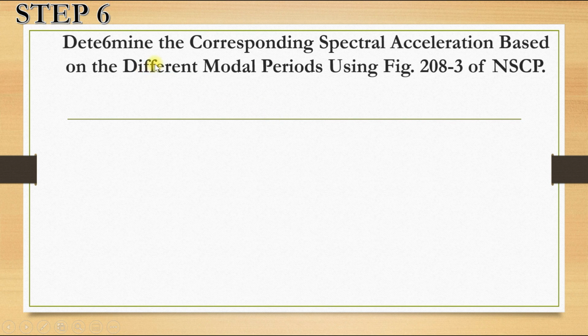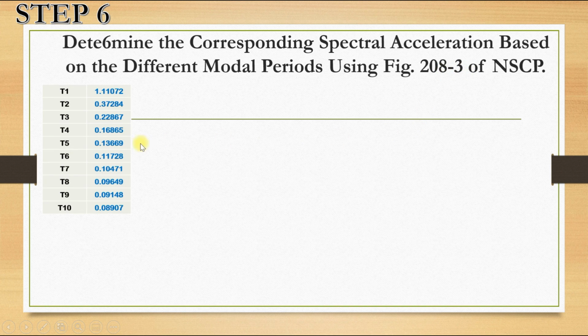So for our step 6, we have to determine the corresponding spectral acceleration based on the different modal periods using figure 208-3 of NSCP.